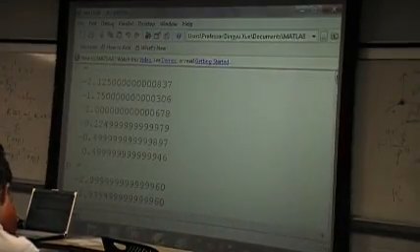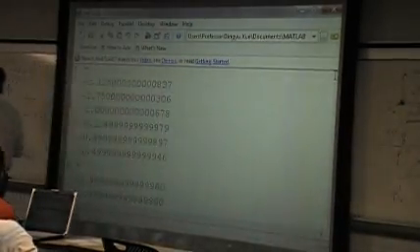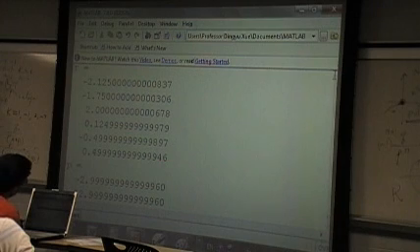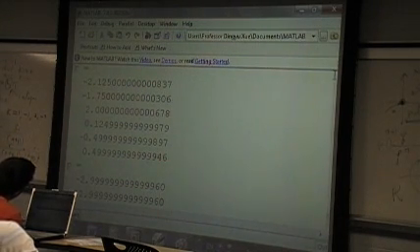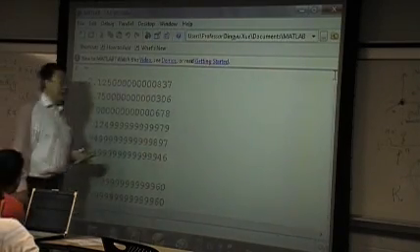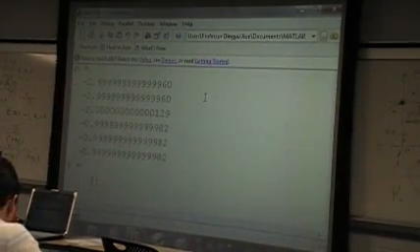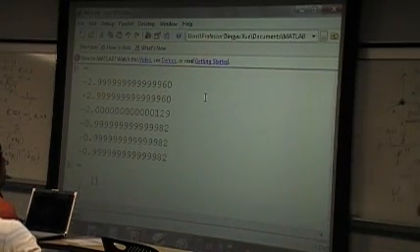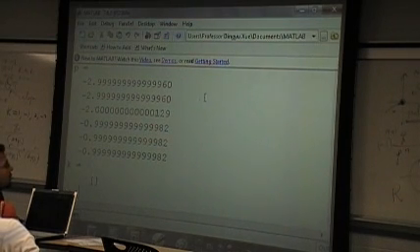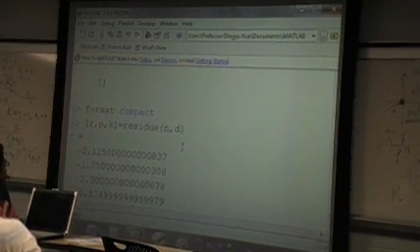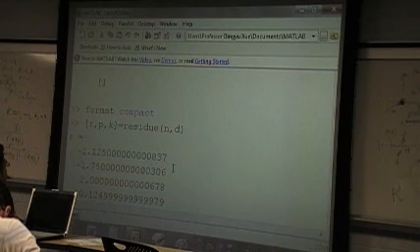The r vector is in fact the numerators at each of the poles here. In this way we can easily express the original function in a partial fraction expansion form like this. And what is the argument k? k here is the empty matrix, indicating there are no other terms besides these partial fraction terms. So in this case, we can easily find the partial fraction expansion of the original rational function.